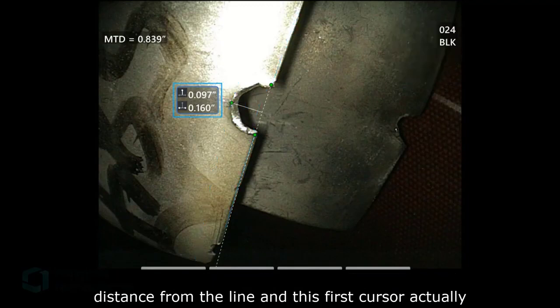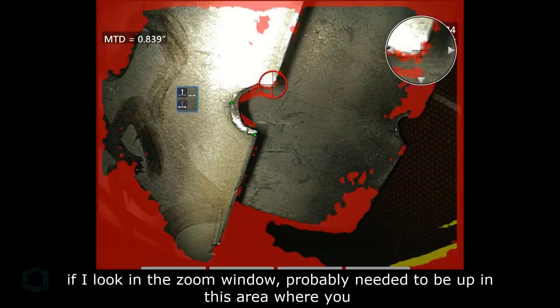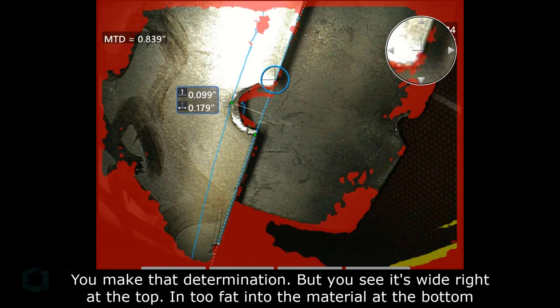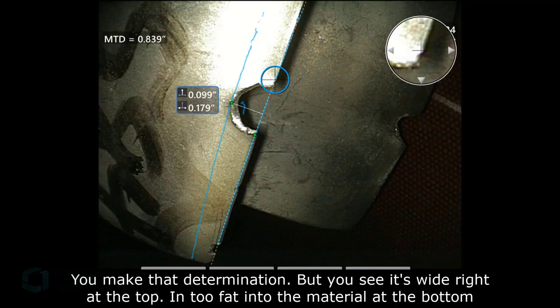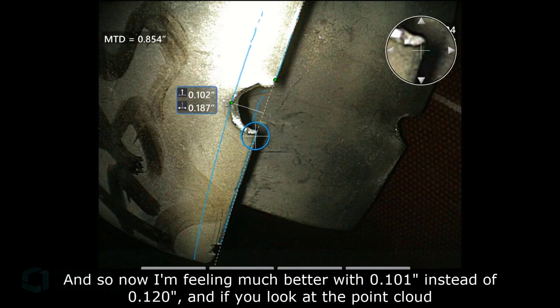And this first cursor, actually, if you look in the zoom window, probably needed to be up in this area where you probably blend out that damage. Maybe, maybe not. You're the turbine person. You make that determination, but you see it's wide right at the top and into the material at the bottom. So I'll take a look at this and get it out onto what is the leading edge of that blade. And so now, feeling much better with 101 thousandths instead of 120 thousandths.